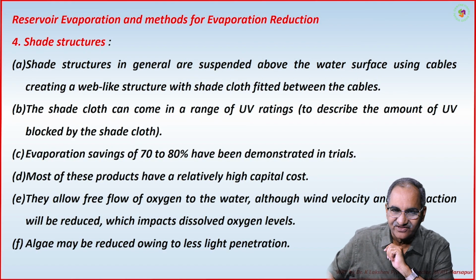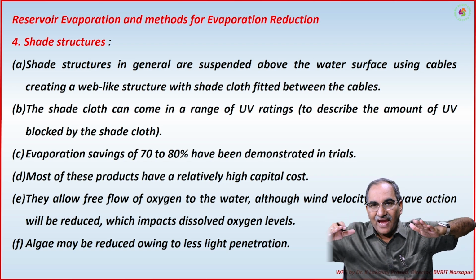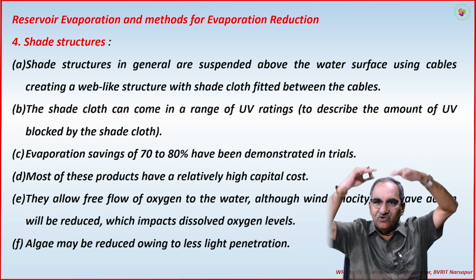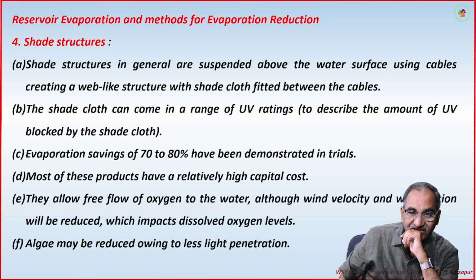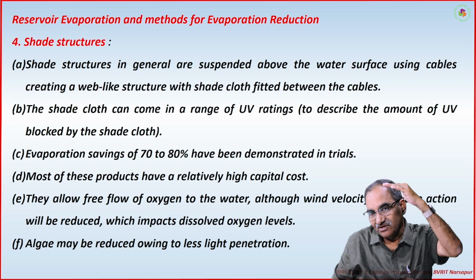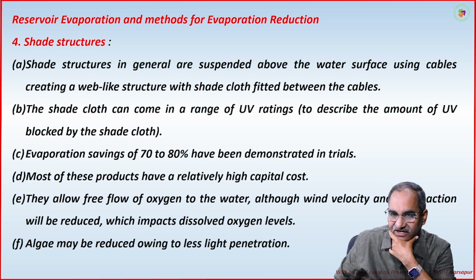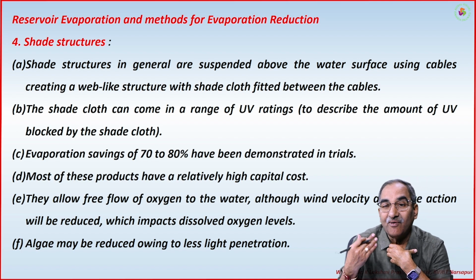Then shade structures. Suppose you construct a shade, for example from the bank onto the reservoir, some dome type structures. In such a case you can arrest the sun's radiation to some extent, thereby reducing evaporation losses.